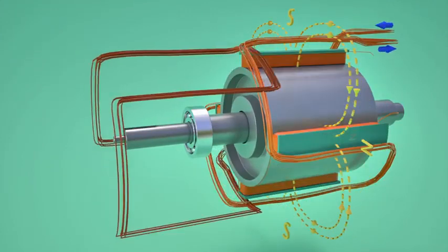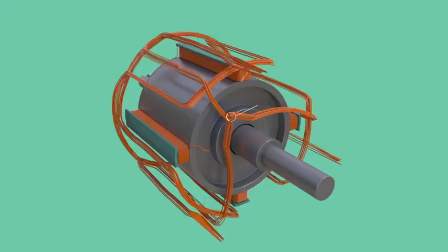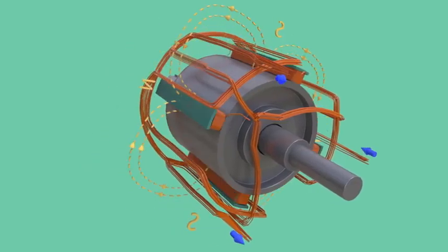For producing 3-phase AC current, 2 more such armature coils which are in 120-degree phase difference with the first are put in the stator winding. Generally one end of these 3 coils are star connected and 3-phase electricity is drawn from the other ends. Neutral cable can be drawn from the star connected end.